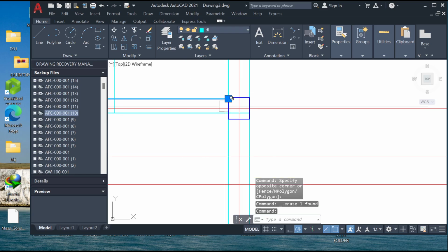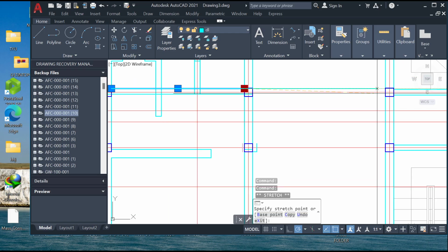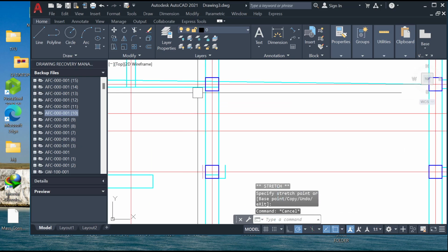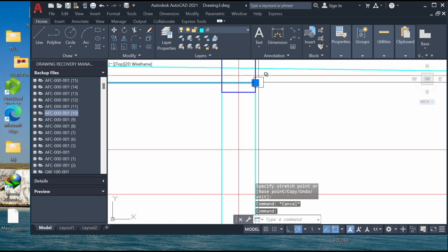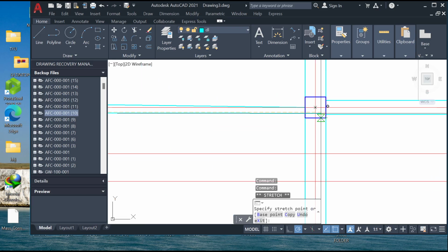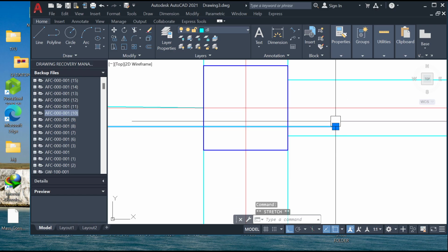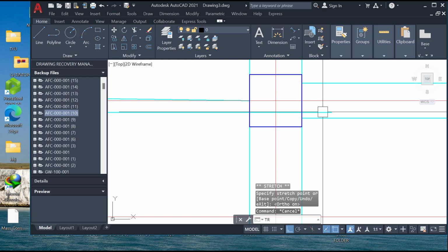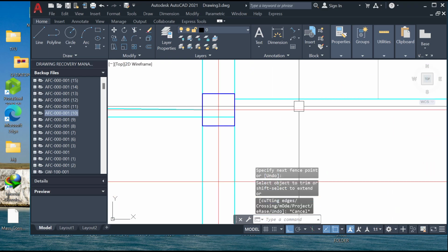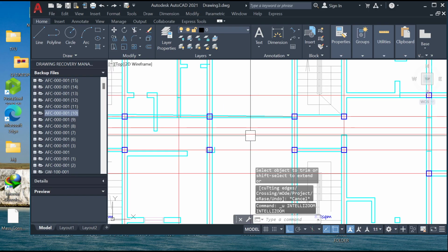So I can just come here and just drag this here. I don't know if this is at the top. Okay, just drag this here. Then come here too. Because the wall is a 150 wall, that's why you see that it's not flush with the end of the column, but there's no problem. I'll show you how to go about it. Now come here, let me do Ctrl Z.